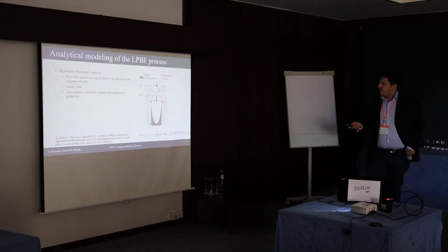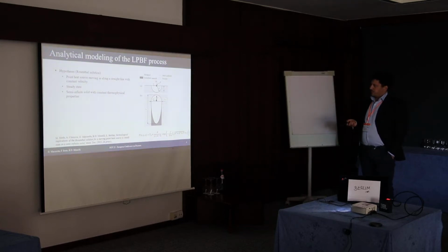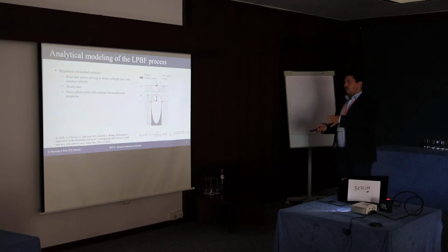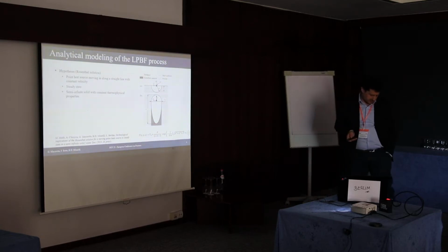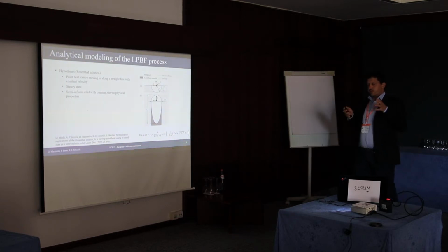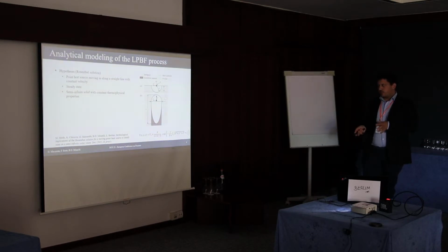This is about the development of the process parameters. I used an analytical model of the selective laser melting process that exploits the Rosenthal solution. It's an approximate solution, but it can provide an analytical prediction of the thermal field that we have in the material.